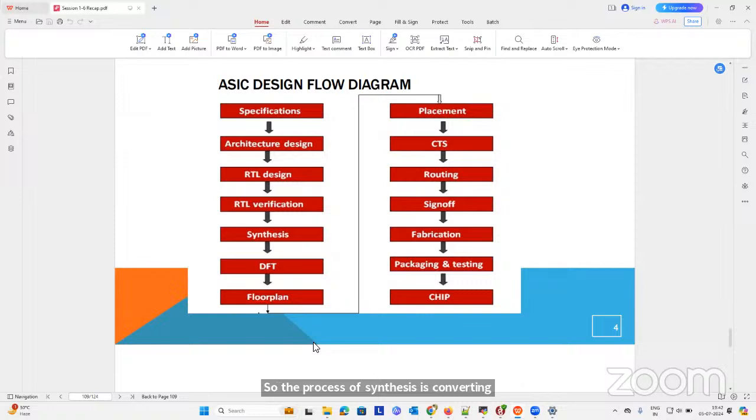Once the synthesis is done, next is the floor plan. Before going to the floor plan, we insert scan cells in the synthesis netlist. That is how we learn the concept of DFT. Floor plan is nothing but deciding the chip die area and core area. Once the die area and core area are decided, we place the standard cells and macros in our design, and placement is completed.